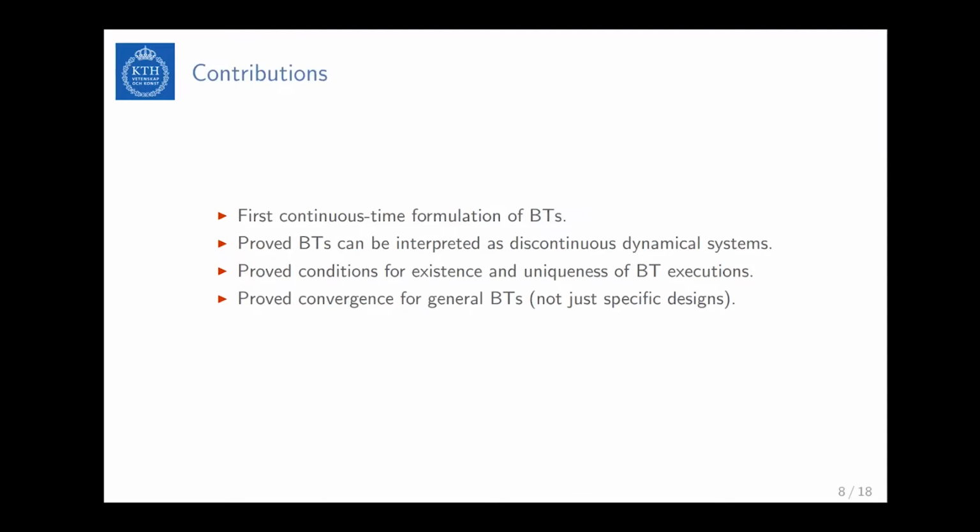So guaranteeing that the trajectory of your system under the behavior tree controller is actually unique, so you can actually analyze it. With these behavior tree controllers, we also prove the conditions under which they would make the system convergent. Say you have some AUV mission that involves multiple different tasks.